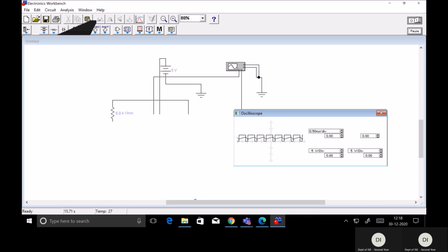And there is another waveform, that is the Sawtooth waveform, which we got from the capacitor. The CRO has two channels, right? So channel 1 positive is connected to the output of the 555 timer IC, that is to the third pin. Another channel, the channel 2 positive, is connected to the capacitor to get the capacitor waveform.